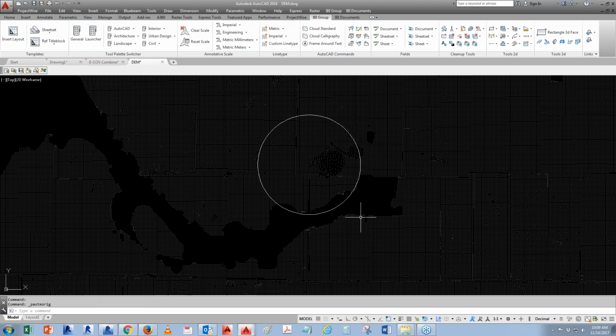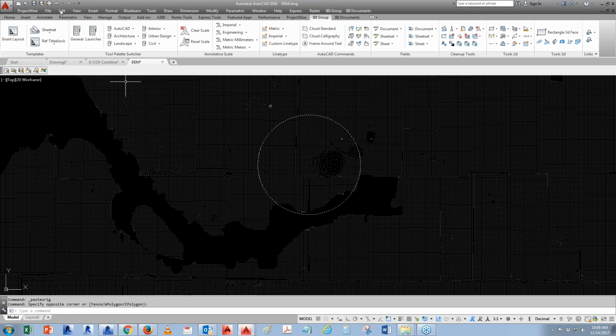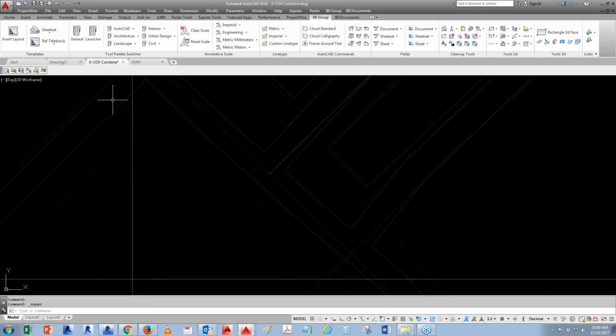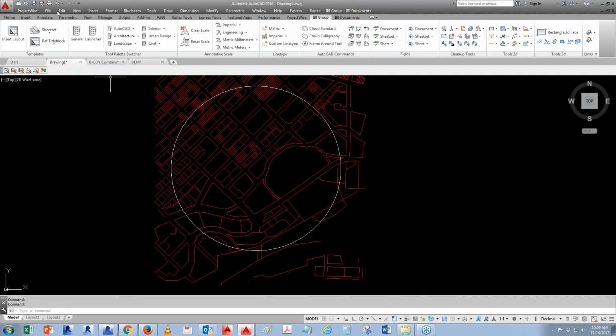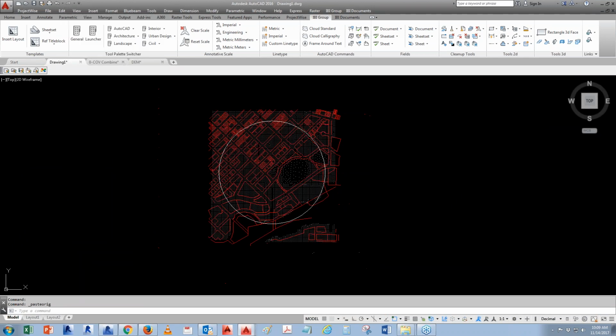Some other jurisdictions only use contours. Right. So how you do contours is that you do it exactly the same. You just basically put this in. And what you want is to select that and say edit, copy base point, and go 0, 0. Okay. Next thing you want to do is go back to the same drawings and edit, paste coordinates. And this is what you have.